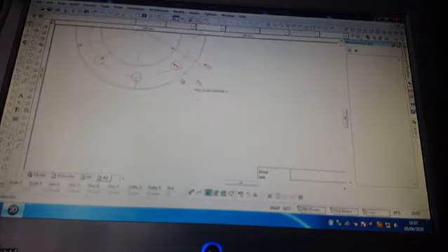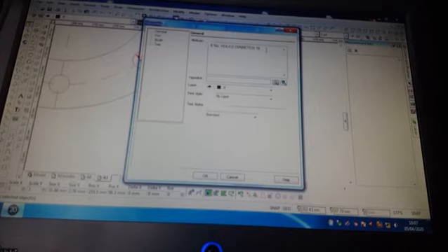Now, because it says nothing about thickness, not much point in drawing an end elevation, but I think I'll put some extra notes on here. Thickness 12.5mm. You could also infer you're in metric, so you don't need the millimeters.